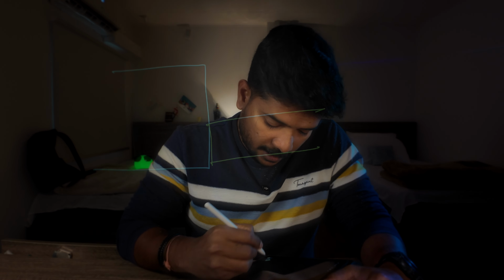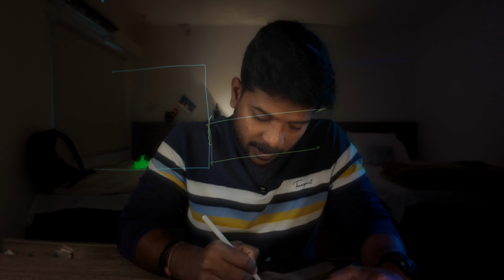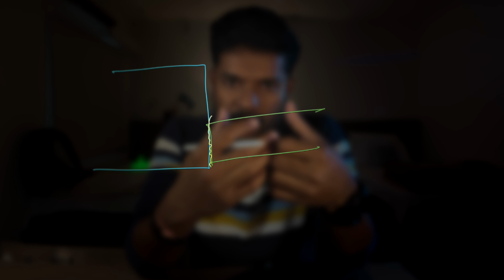Bimetallic corrosion happens when two dissimilar metals are in contact with each other. When two dissimilar metals are in contact and there is moisture between them, this basically forms a battery. How? Well, every metal has its own potential. When two dissimilar metals are touching each other, the potential difference between them and the moisture in between, which acts as an electrolyte, forms an electrical connection. And this electrical connection helps the electrons to flow from one metal to the other.